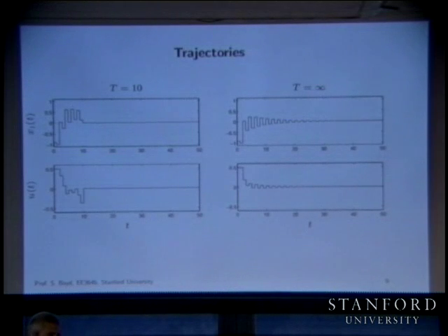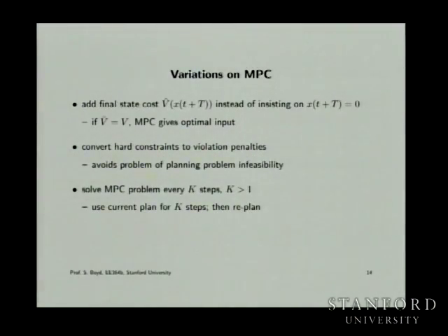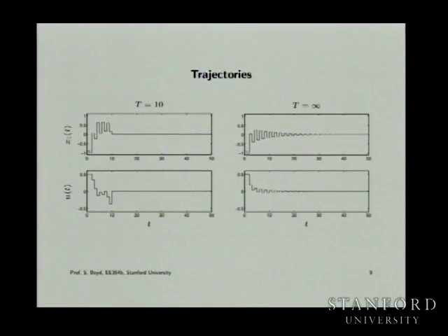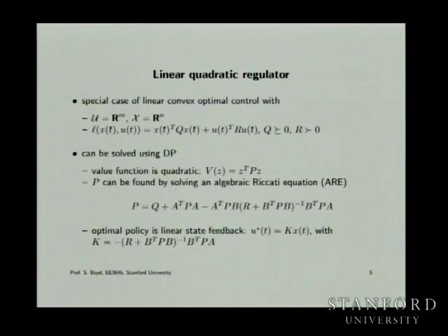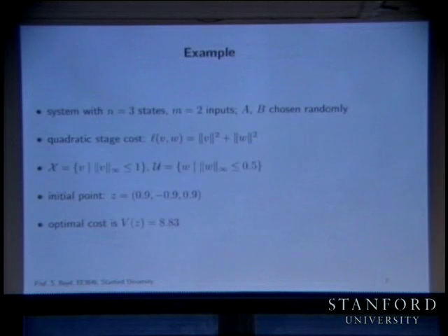This is just an aside, but just for fun, if you have the background. You can show in a problem like this that you can compute an ellipsoid in state space such that if you're in the ellipsoid, the optimal control in fact coincides with the linear one, because you'll never saturate in the future, and therefore from then on it's given by an explicit formula. In fact, it's this formula right here. This is an advanced topic, so just ignore me if you don't know what I'm talking about. Also, I'm going the wrong way. There we go. So it's given by this formula. And once you have that, you can actually evaluate the cost to go by solving a Lyapunov equation. So if you knew what I was talking about, fine. If you don't, just ignore what I just said.